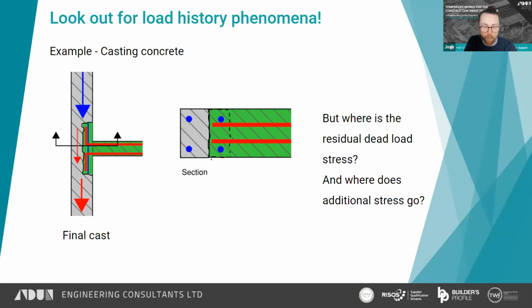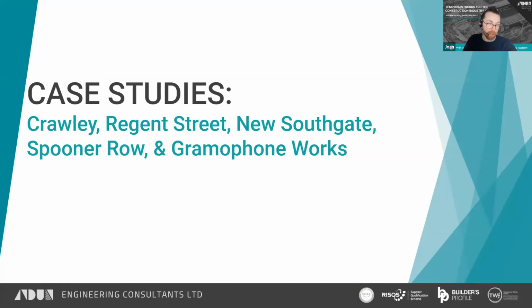To sum up, once a structure is taking load, you cannot remove this load without some form of jacking or preloading. And casting wet concrete into this section does not remove any loading that's already there, although the new structure will take any additional loading that's added on top after it's cast. This is a valuable lesson that applies to construction and jacking, propping, especially back propping during reinforced concrete floor construction. So that's everything I've got to say so far on the subject in today's webinar.